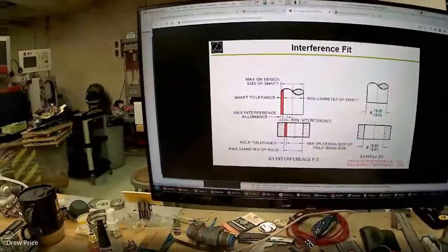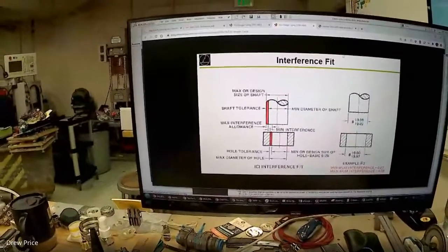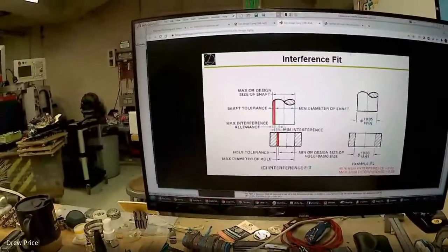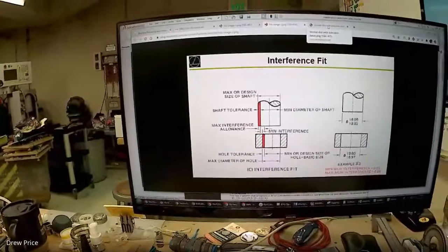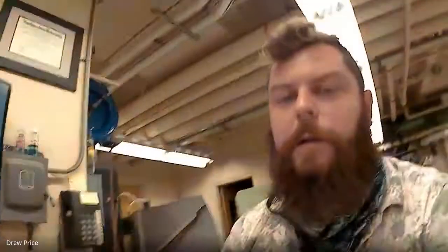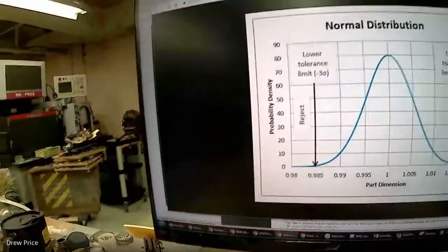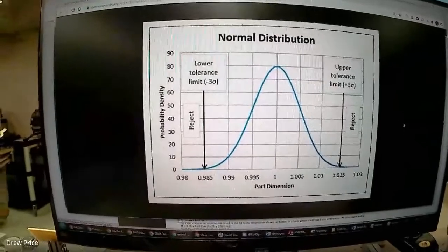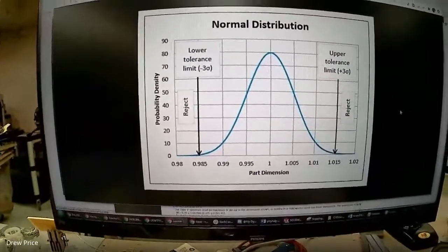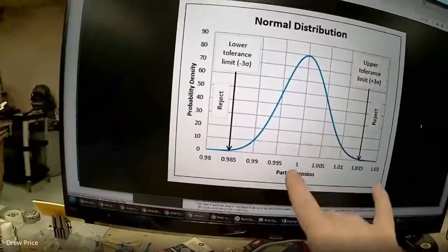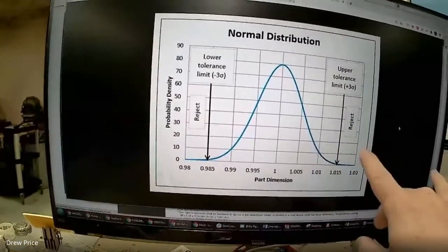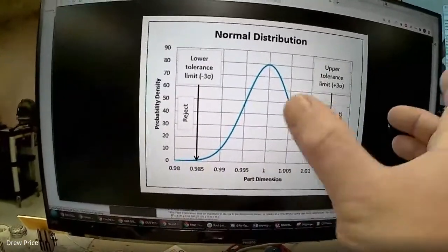So the last comment that I have to make about tolerances as you go through your manufacturing is that tolerances generally are given as some range. Either the particular process or machine will have a range of some amount that it can produce, and that's usually the bounds of the range. So like a lot of things in the sciences, tolerances can be really adequately described by a normal distribution with some number of standard deviations dictating where the parts lie.